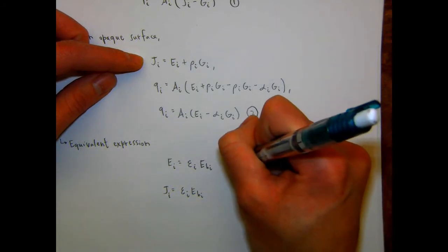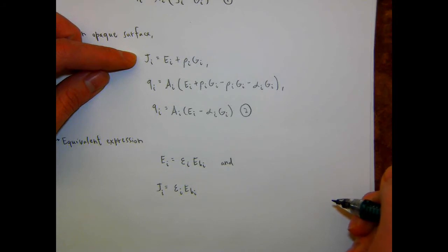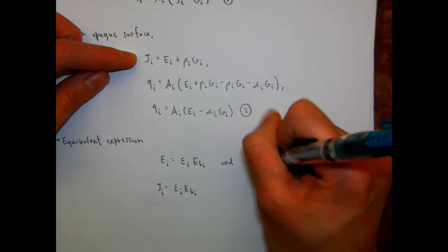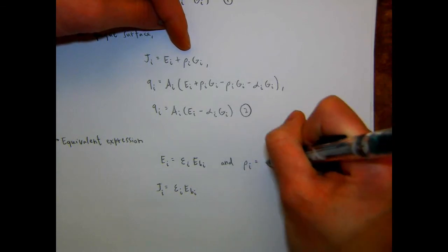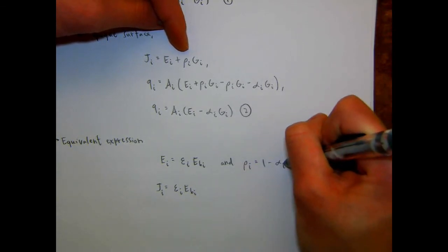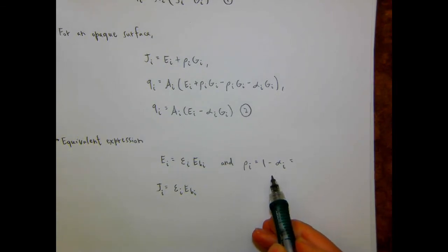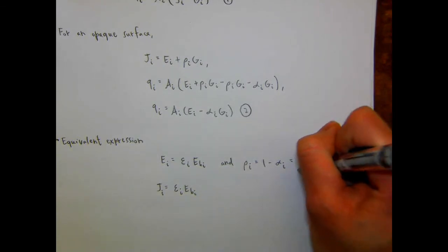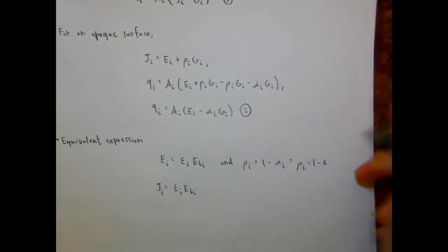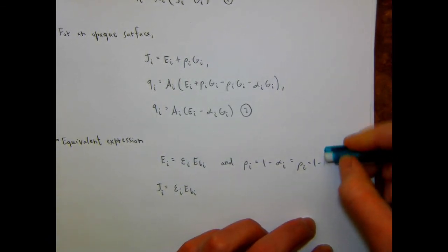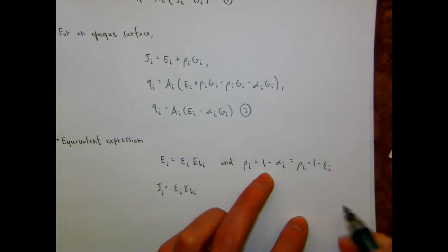And then for the opaque diffuse gray surface that we're considering, the reflectivity for an opaque surface is going to be 1 minus the absorptivity. Since there's no transmissivity, reflectivity and absorptivity just equal 1. And then given our assumptions, we're able to say that that is equal to 1 minus the emissivity, since these two quantities are equal.